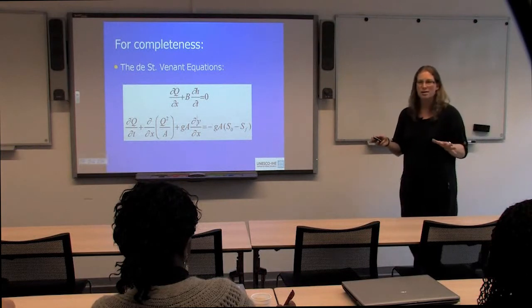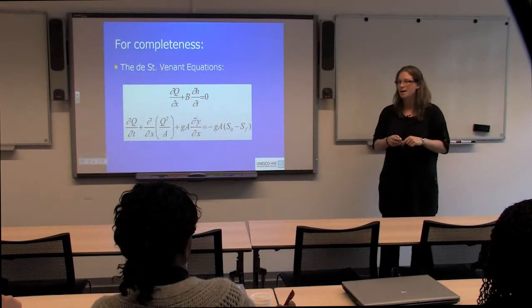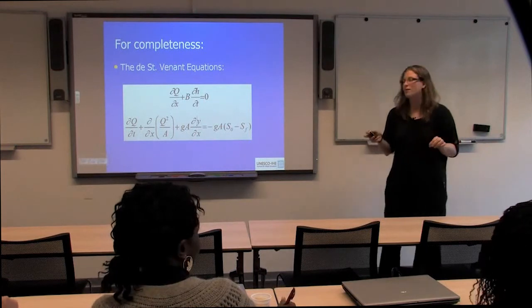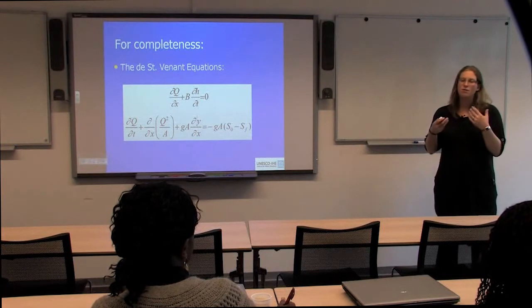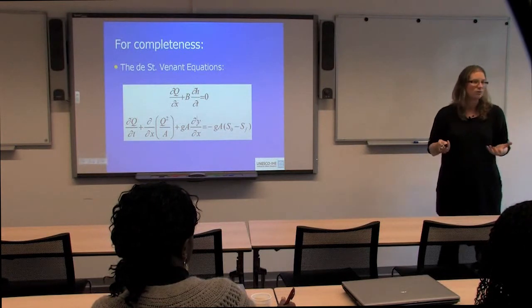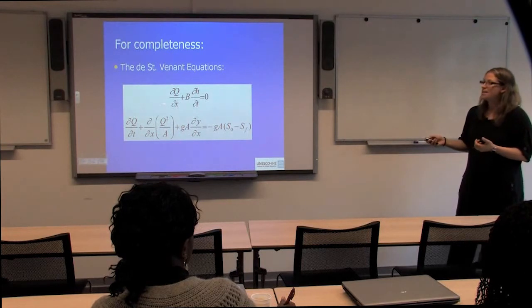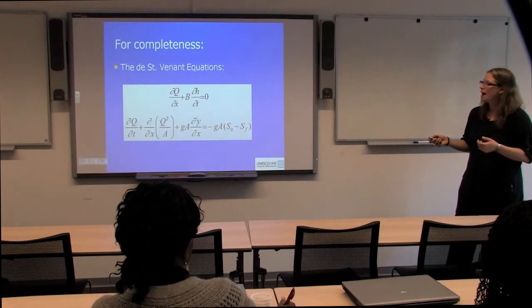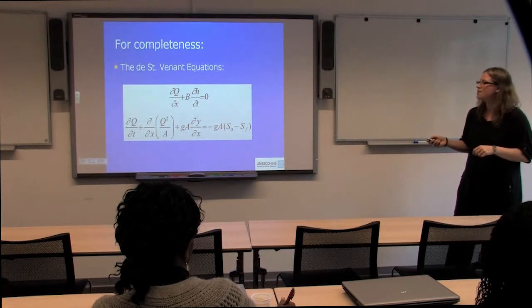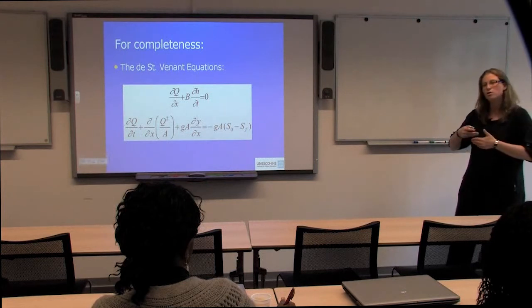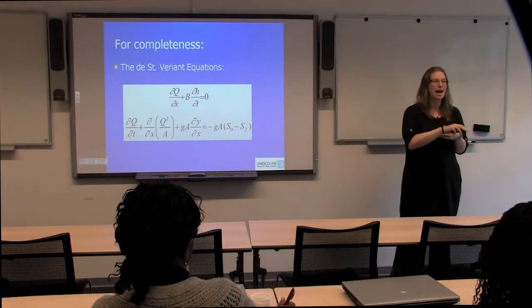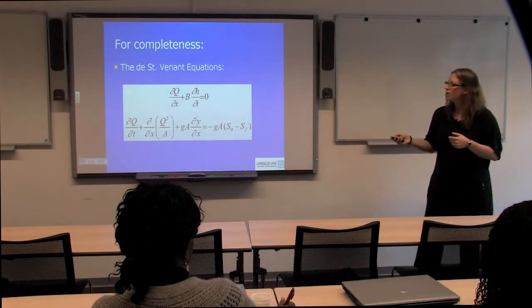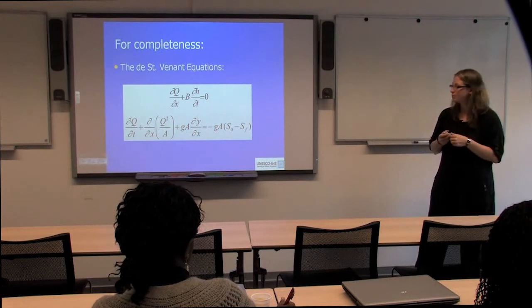Have any of you heard of the Saint-Venant equations? Yeah? So we've got a good covering. The Saint-Venant equations are the basis for one-dimensional modelling of hydraulic flow. They are basically partial differential equations in terms of x, distance along the channel, and in terms of t. These are one-dimensional here, you can also make them two-dimensional. In two dimensions you're taking in components of velocity in x and y. And here, in one dimension, we use the component of q.